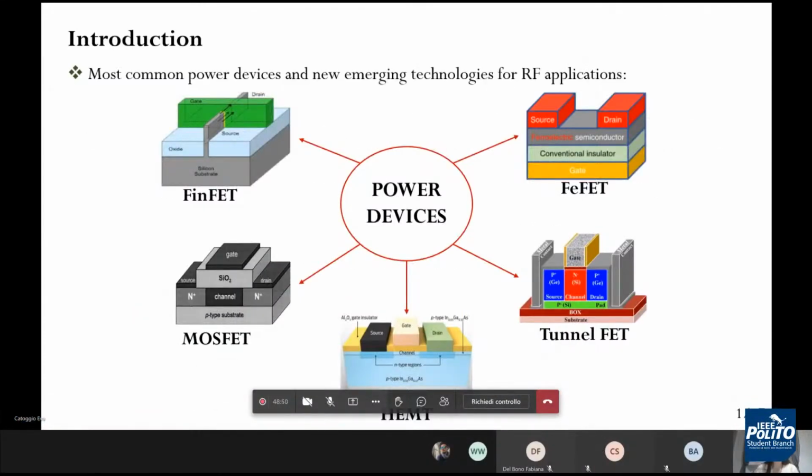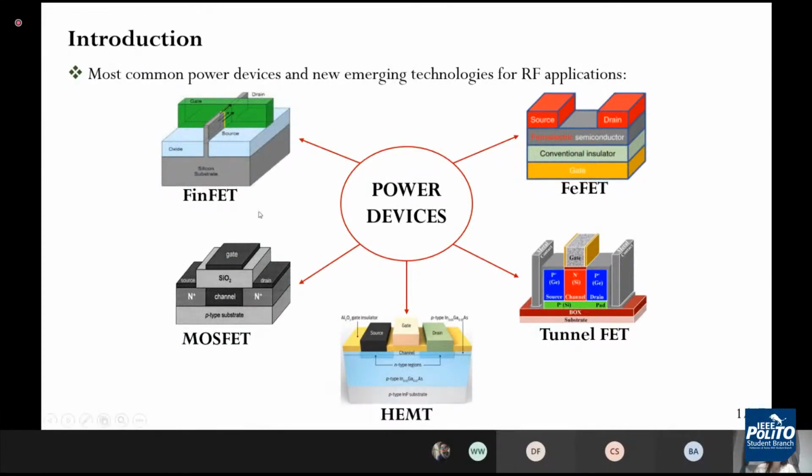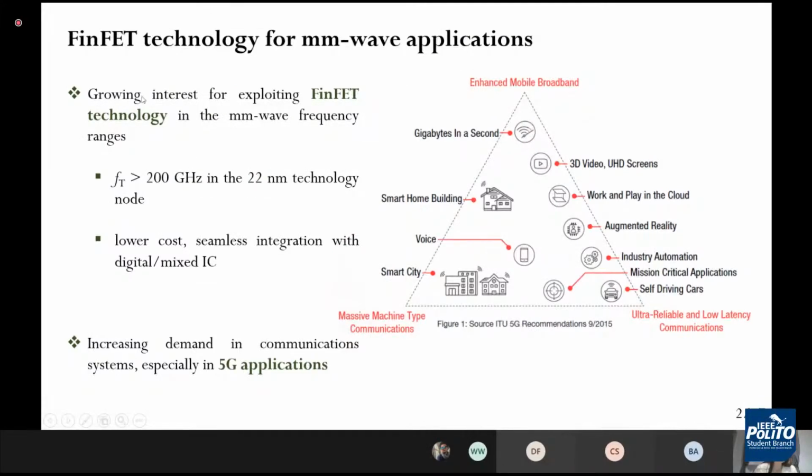The most common power devices in RF applications are FinFET, MOSFET, HEMT, but also new emerging technologies such as tunnel or ferroelectric FETs. In the last years, there is a growing interest in exploiting FinFET technology in the millimeter wave frequency ranges, especially with reference to 5G applications, thanks to their high cutoff frequency and their lower cost.